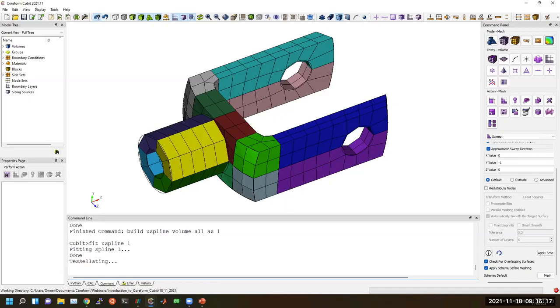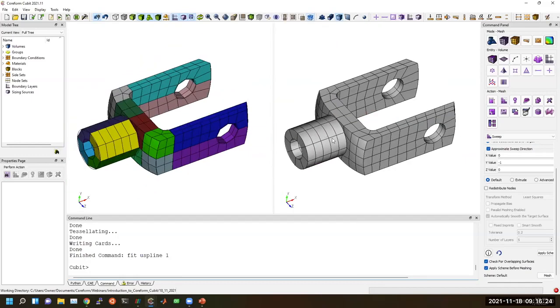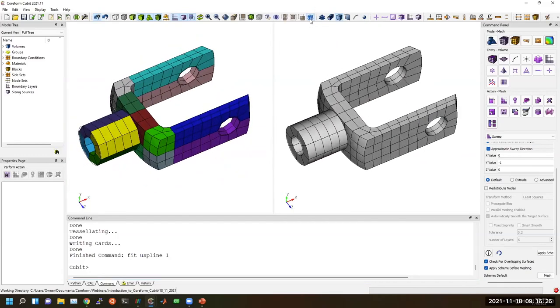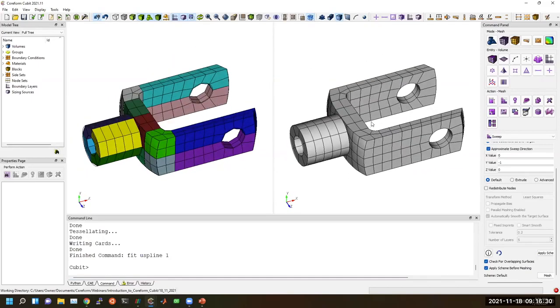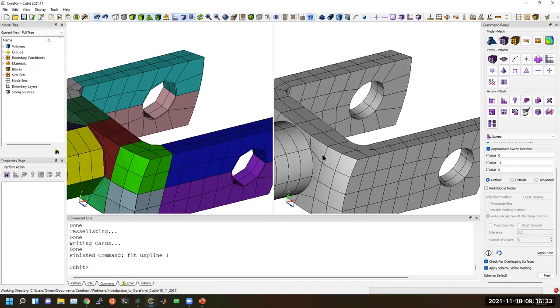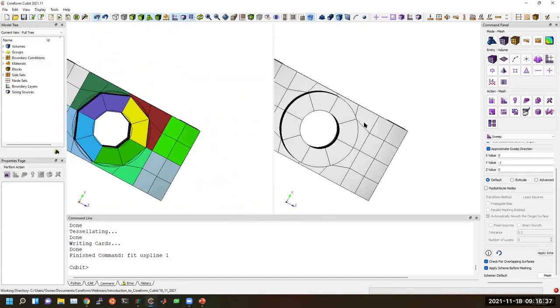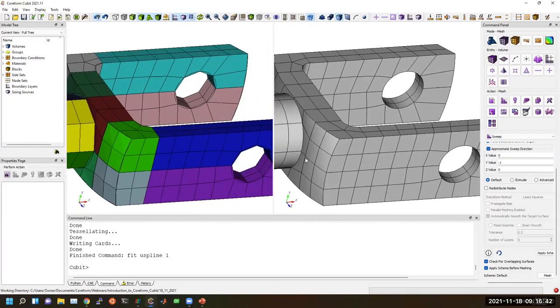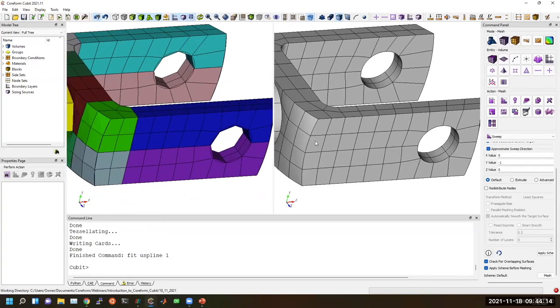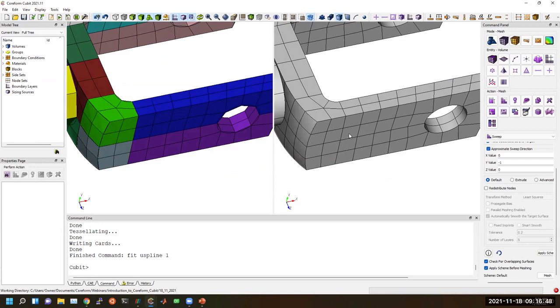And now we're rendering. You can then view the finished U-spline inside of Coreform Cubit through our U-spline view. And so as you can see, because we're using a higher order basis here, quadratics or degree 2, we get a really good fit to the input geometry, as well as, again, smoothness in our bases across these element interfaces.